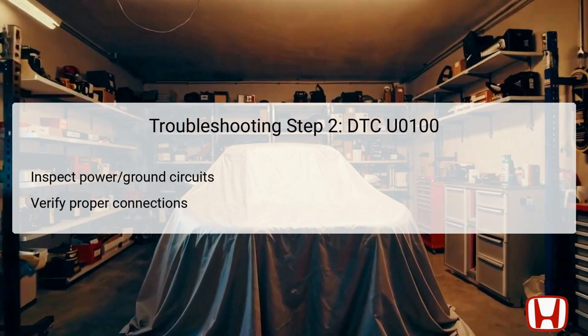Technicians should utilize a multimeter to confirm voltage levels and ensure connections are secure and free of corrosion. By addressing these foundational issues first, technicians can prevent unnecessary replacement of modules and swiftly resolve the communication failure.